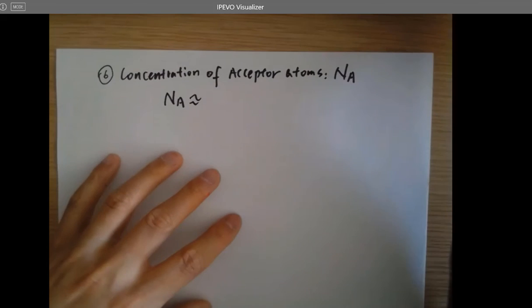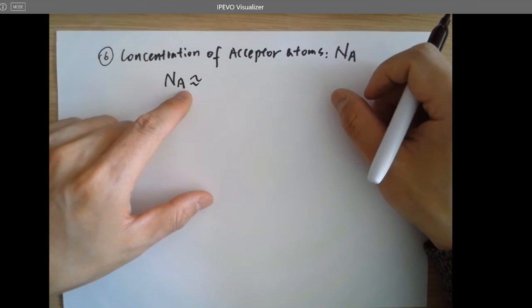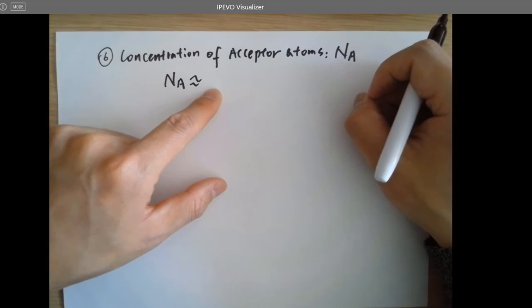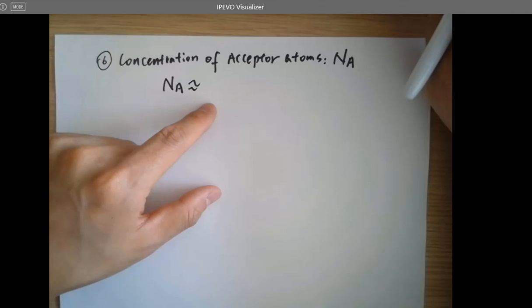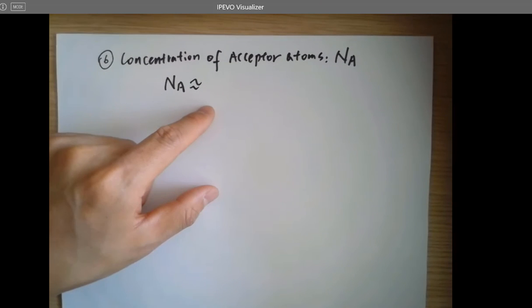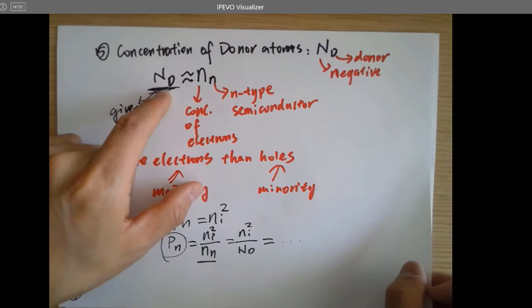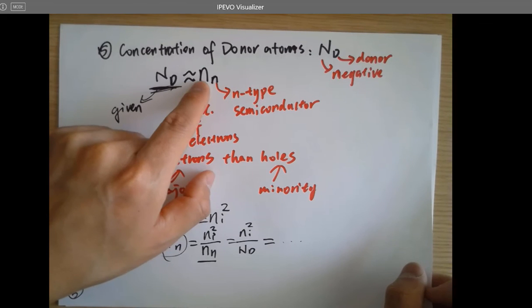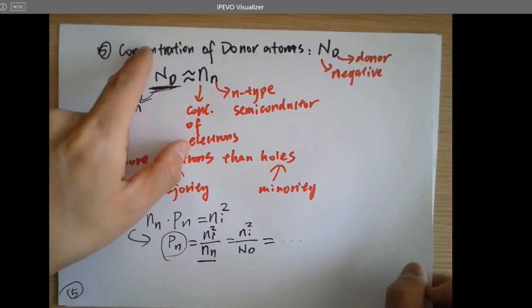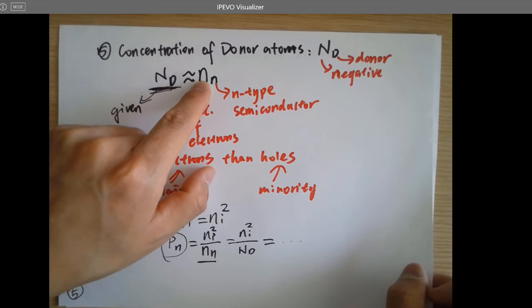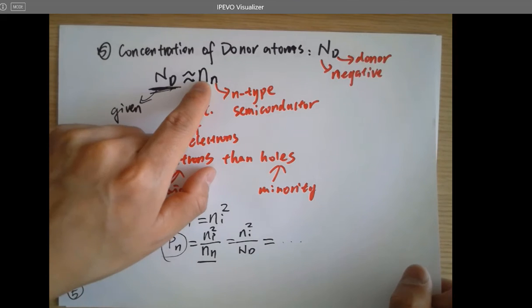So for the acceptor, for the p-type, positive, right? P-type. Na is pretty much what? Np? Is that making sense? Why is it Np? For Nd, it's a donor, equals Nn, because it's N-type and the electron concentration. So for the p-type, it's going to be Na equals P, which is the holes concentration, because every boron atom is going to contribute one free hole.